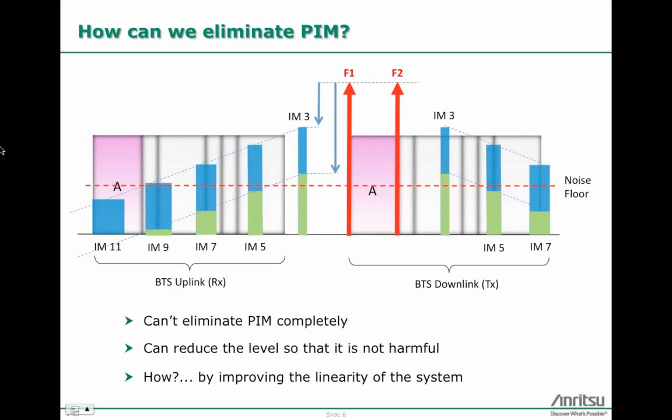Now, what's shown in the picture above is that if I look at the arrows, one of them is showing a beginning linearity, and I drive the linearity down, and you see all these intermodulation products decreasing as the linearity of the system is improved. This actual picture represents the PCS block of the 1900 megahertz system in the United States. And if you notice, if I'm an A block operator running in a PCS system, the intermodulation product that actually falls in my band is IM11.